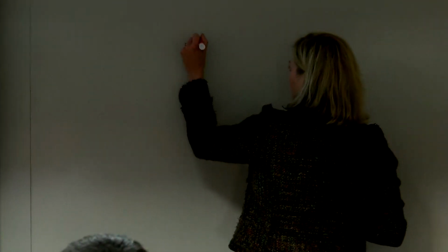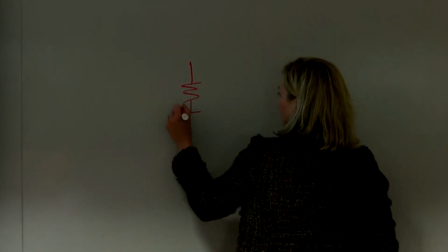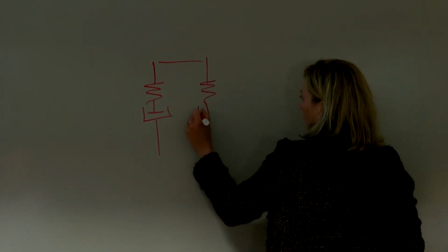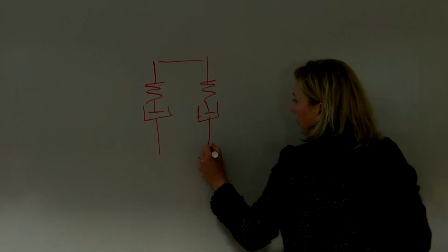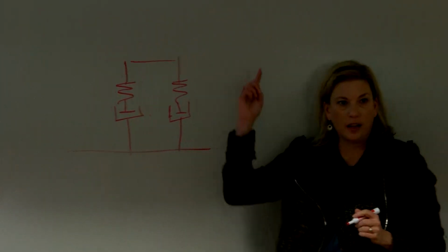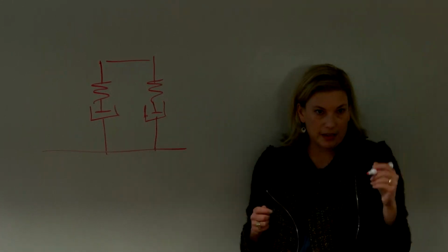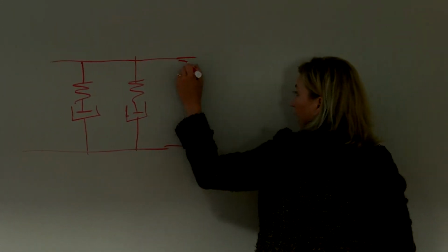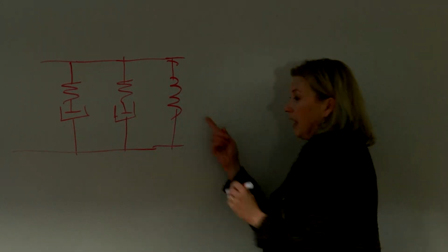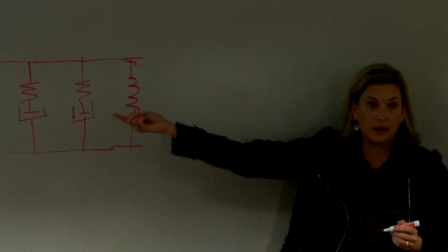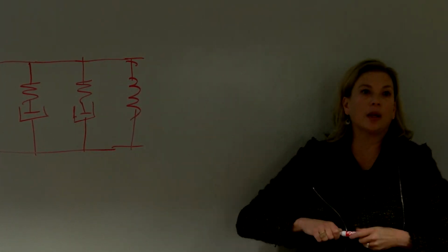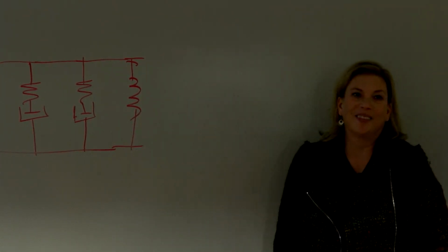With two linear springs and dash pots, you can model the viscoelastic response that we saw. So it had two time constants of relaxation, but they were linear, and the nonlinearity came in the elastic part, which you see clearly in the experiments. That's our viscoelastic ligament model right now.